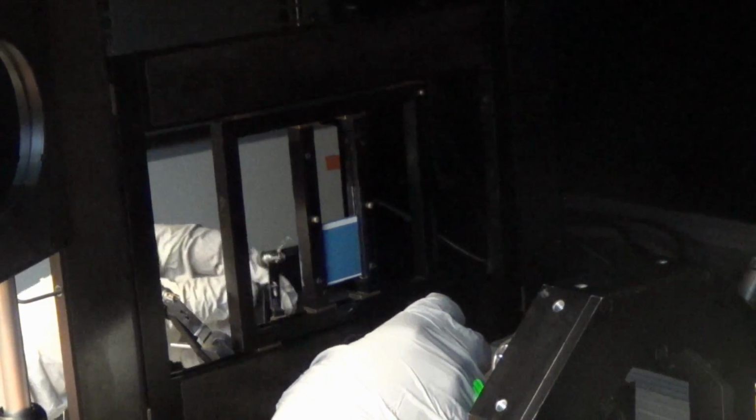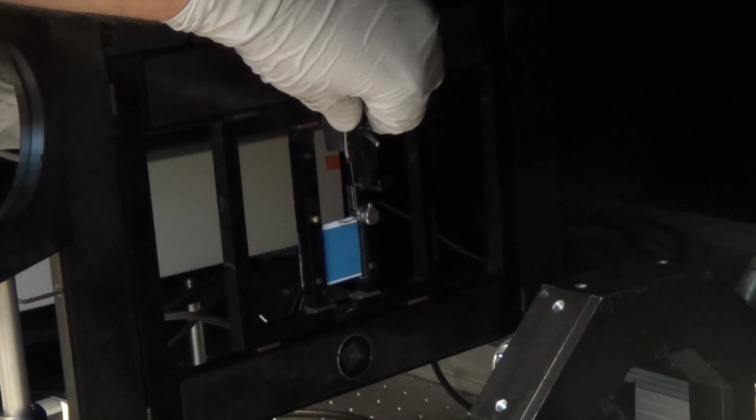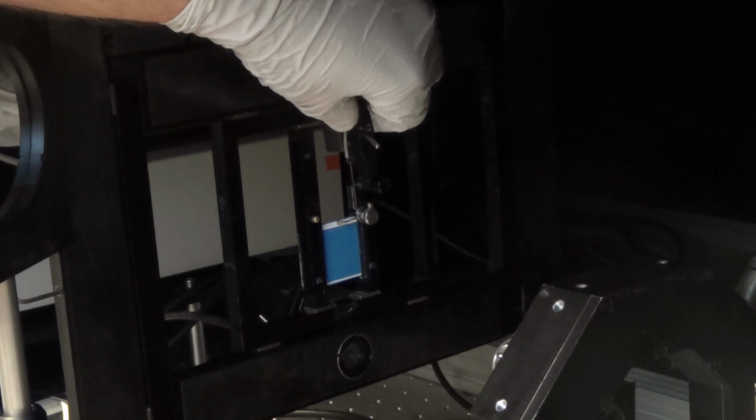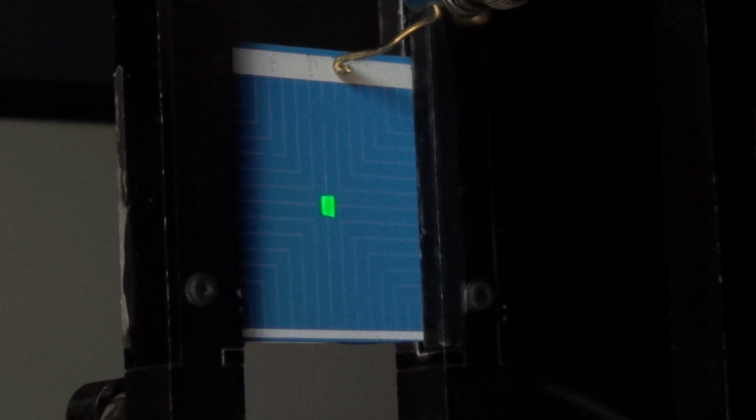This mounting frame is isolated such that no current can leave the cell unnoticed. Contact probes with gold tips are placed on the back contact and on a bus bar at the front side of the cell. The light spot is then placed at the middle of the cell where no contacts are present to avoid shading losses.